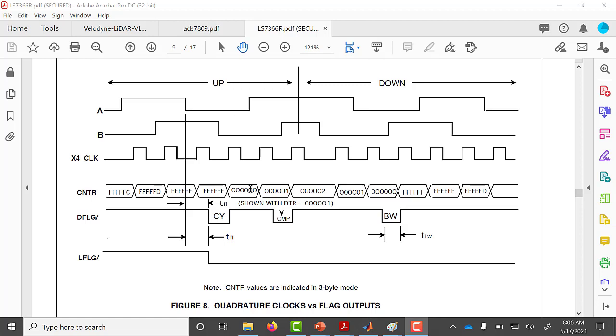And you get the data into your microcontroller, and the data looks like 32-bit data. They're only showing, I think, 6 nibbles here, but you get signed 32-bit data directly into your controller, indicative of the position of the motor.